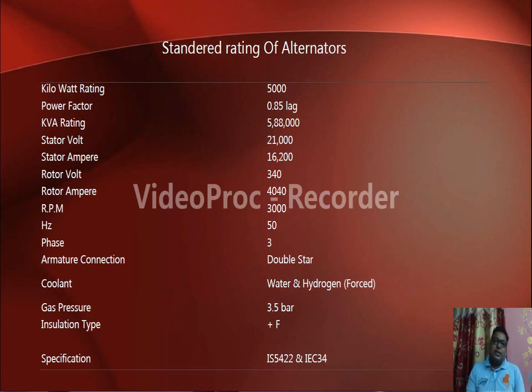This is the standard specification of our alternator. Kilowatt rating 5000, power factor 0.85 lag, kVA rating 5880, then stator slot, stator ampere, rotor voltage, rotor ampere are mentioned. RPM, the speed of the machine, and frequency in hertz are mentioned. It has 3 phases, and the armature connection is double star.